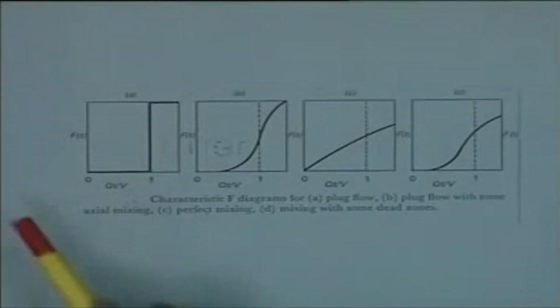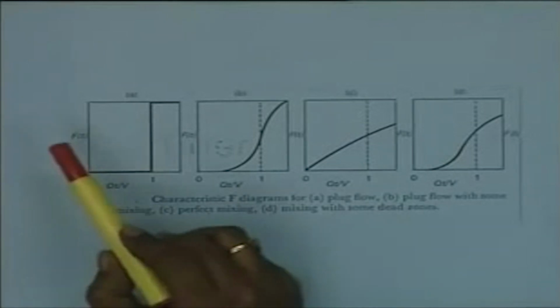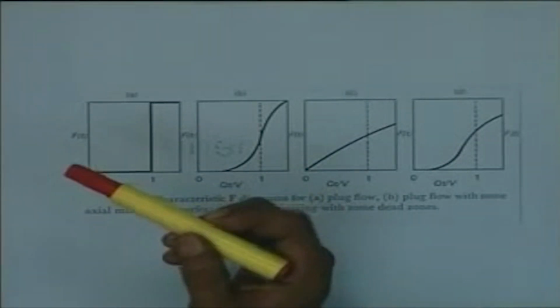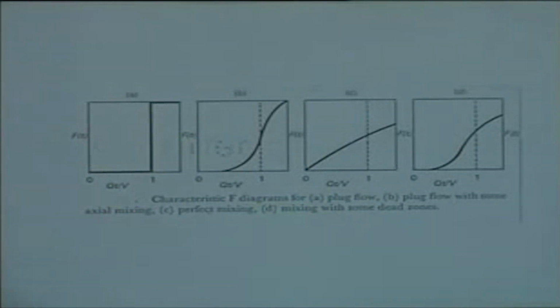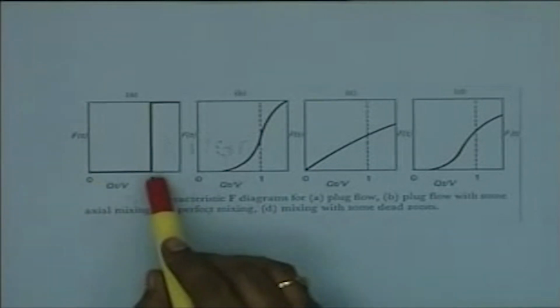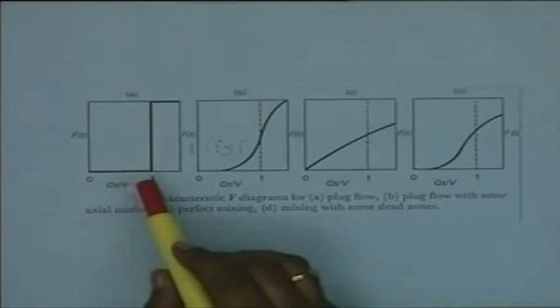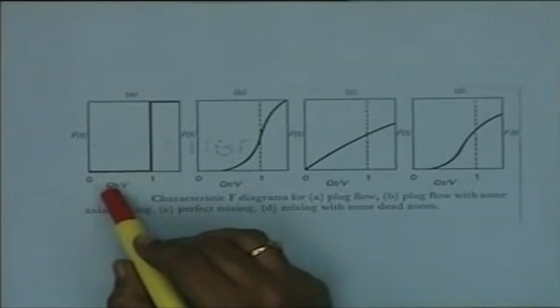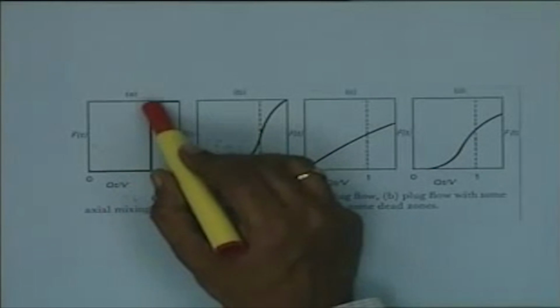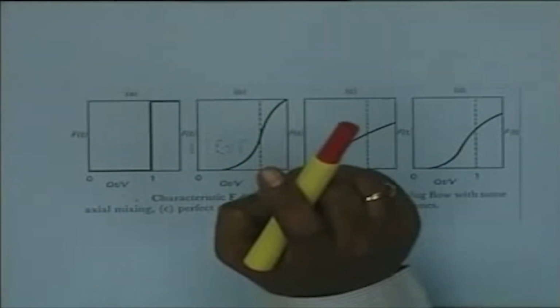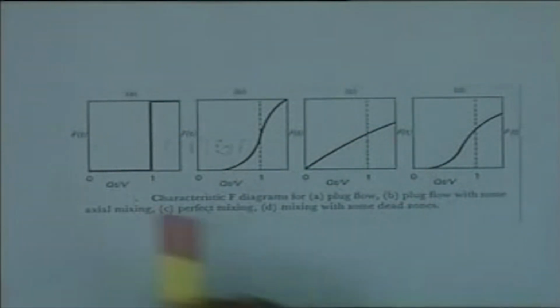That means as soon as the substrate or tracer concentration in that plug flow reactor has been inserted, after time t, or V over Q, that means one residence time, the tracer must come out in the same concentration in the case of a step input.